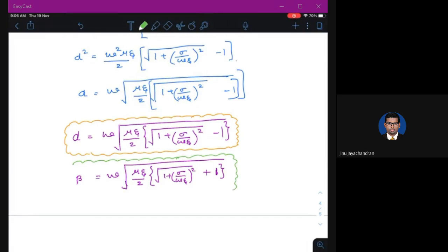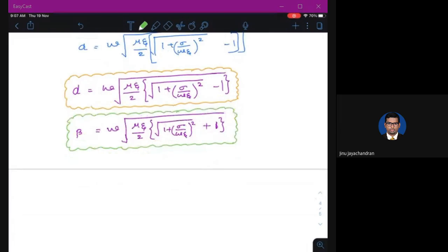We will reuse these equations when we look at different kinds of medium, lossless, low loss, etc. When you have all these kinds of medium, you will see that the equations become very simple. So alpha will be like omega root over mu epsilon. That's all. So this is a general derivation. You can use it in any kind of medium if the medium is not specified. But if the medium is specified, as lossless or lossy or something like that, then you can substitute those values and you will see that the values of alpha and beta are very simple expressions, omega, mu, epsilon, or something like that.